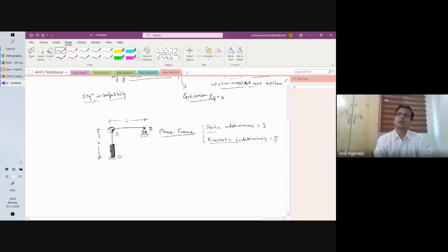So as an answer to that, why did we choose these? As soon as I change the thickness or the cross-section properties of this member here in the middle, so that one half is of a different size and the remaining half is of a different size, we immediately picked up a kinematic indeterminacy here, but earlier we were not picking it.